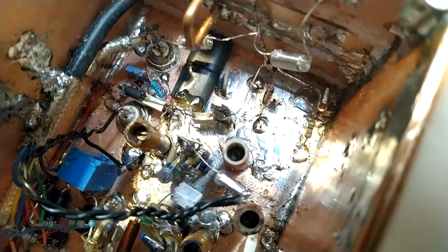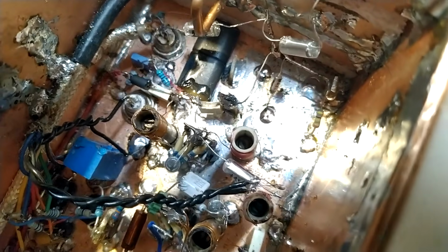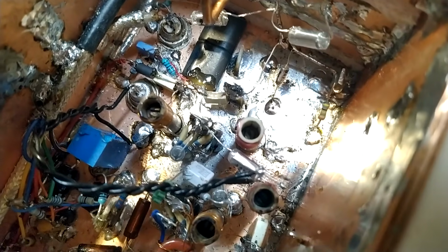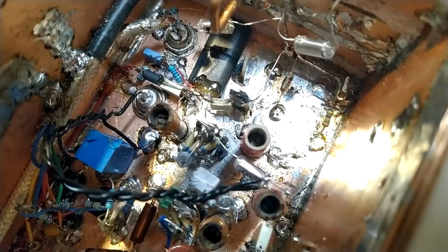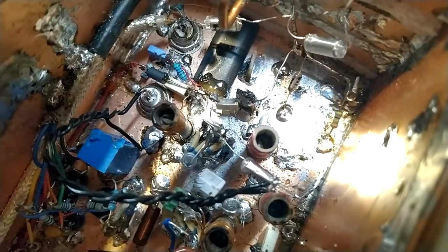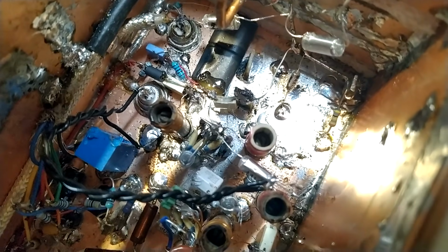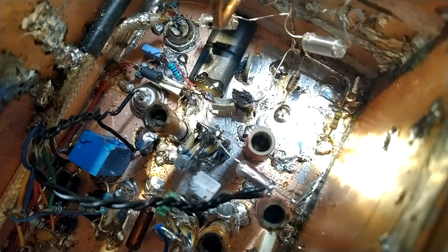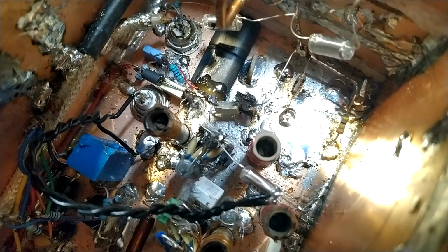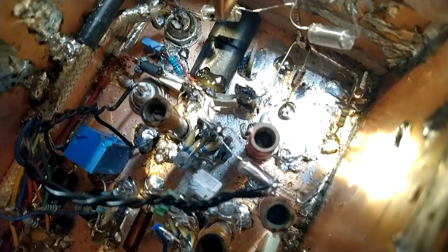I have removed the stop band transformer. It is not needed when the unit is an oscillator. I need it only when it runs as a selective amplifier, when the signal I feed into it has a lot of noise in the stop band, so I cannot trust what I see at the output on the stop band. So now there is no transformer with suspicious glue on it.